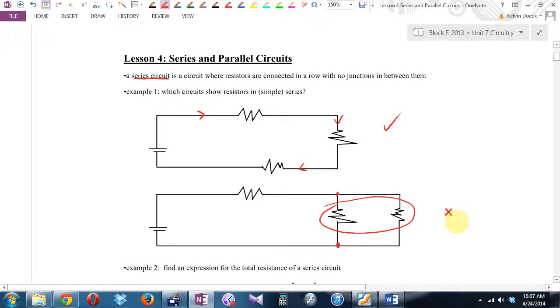Who remembers what I said? If we're analyzing a circuit, if we're solving a circuit, what do we try and find first? Total current. What if they don't give it to us? I said, go look and see if there's a resistor where they gave me two things. What if that doesn't occur? Our strategy now is going to be, can we mathematically rewrite a yucky circuit into the simplest possible circuit? And the simplest possible circuit, don't write this down, has one voltage source and one resistor. One chairlift, one ski hill. That's going to be what I'm going to teach you how to do today.